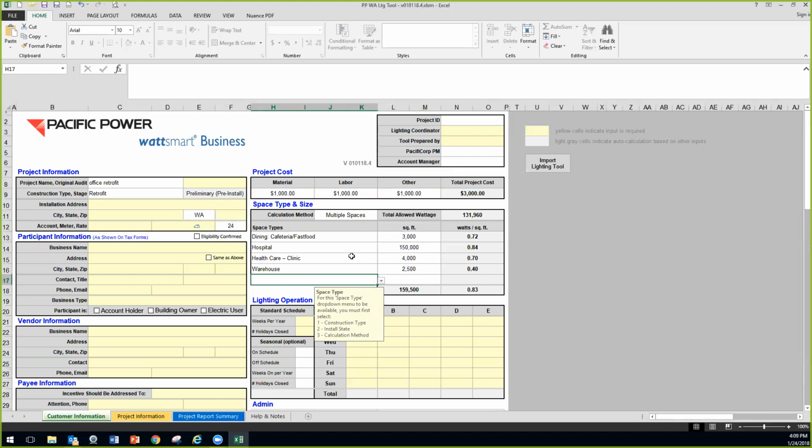If you're taking out 100,000 watts of lighting and going back with 25,000 watts of lighting in your retrofit project, that's going to have an impact on your heating and cooling load for all your equipment inside the facility. It's going to make the heater have to work harder to heat it up in the wintertime and make the air conditioner not have to work quite so hard in the summertime. So it affects your annual savings. So that's why we have to do that.